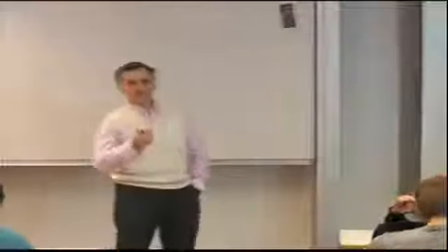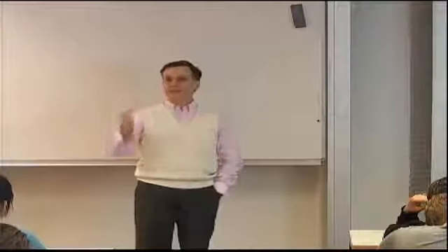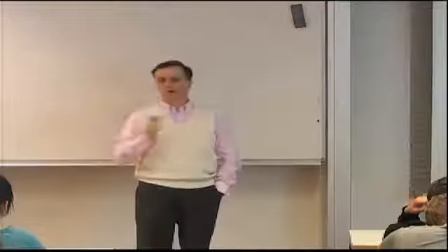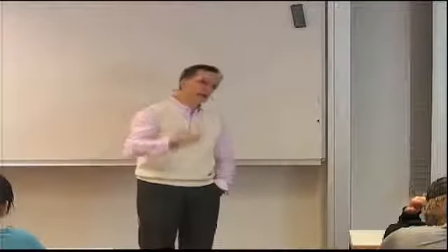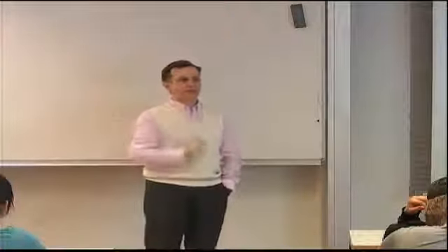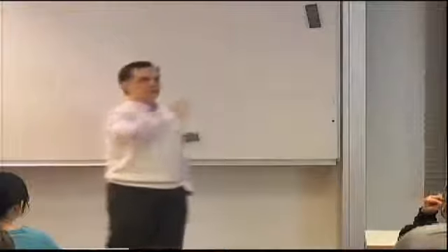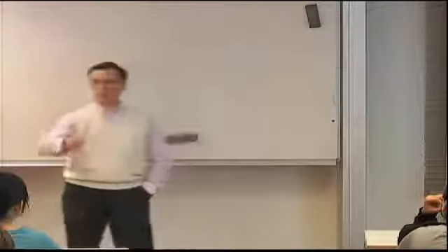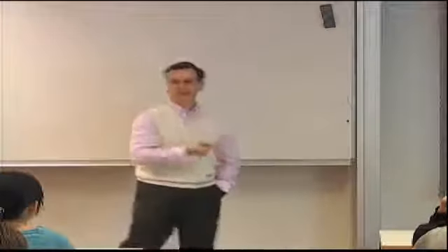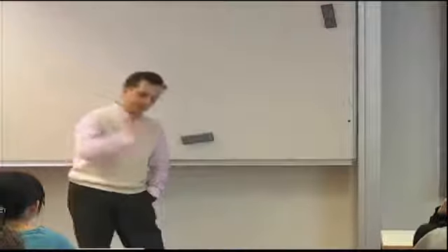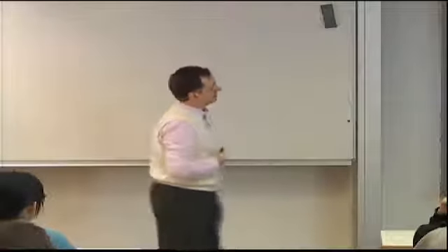And in fact, you need to decide what it is that you want in post-buckling. Someone might argue, I want a very compliant structure that can deflect a lot as long as this is relatively uniform large deflection everywhere. Or someone would say, I don't want large deflection. So don't make a decision about a stacking sequence until you have run the numbers and decided that, okay, for my application in the post-buckling, if I want to postpone failure in this way, I will need the lowest possible stresses. And then you find which laminate gives you that, taking into account also what the buckling load is. So buckling alone is not even half of the story.